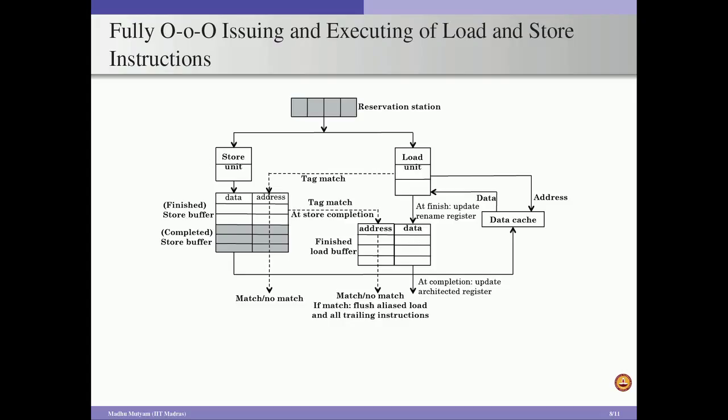In this particular design, we consider a separate load buffer to take care of all the finished load instructions. Again, here we are splitting the load instruction execution into execution finish and execution complete. And at the time of execution finish, we write the data to this buffer. Now we can consider a simple example.